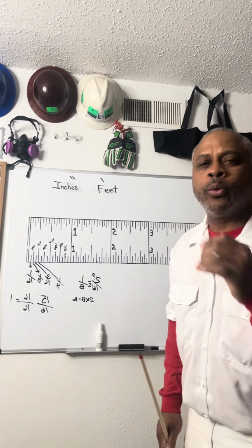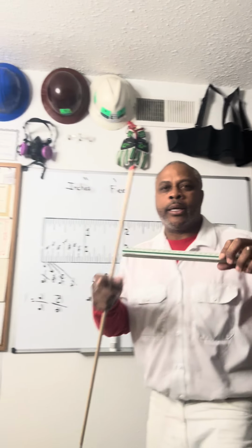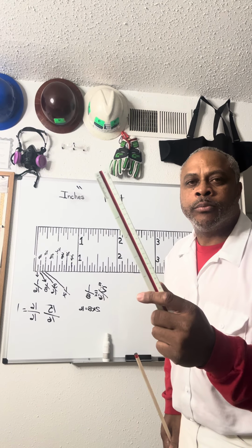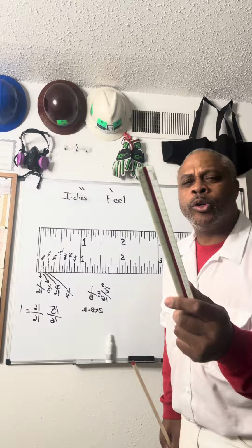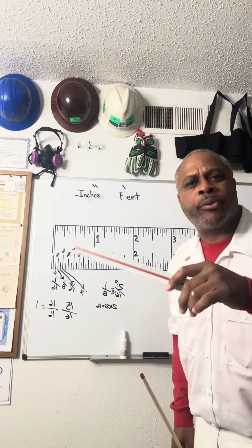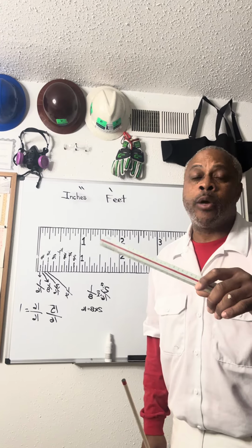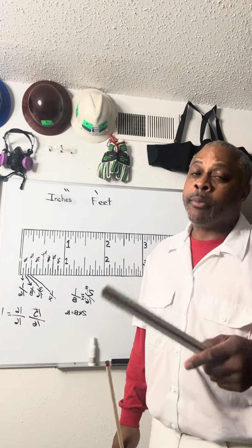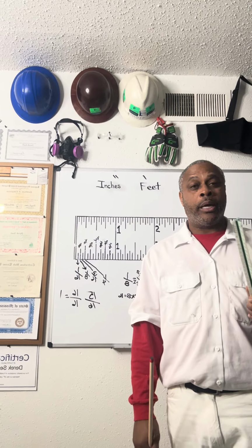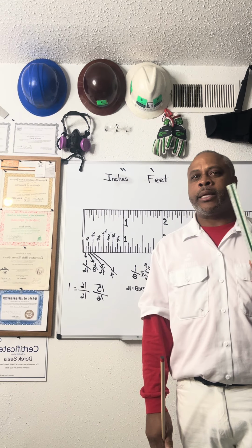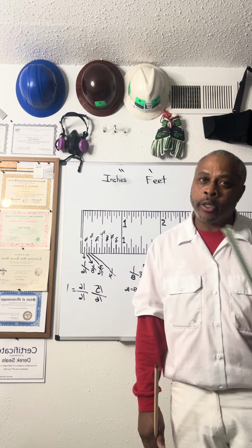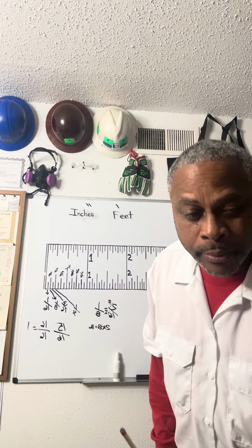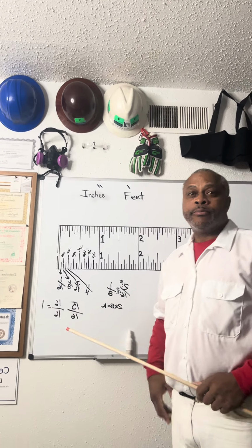We're going to take you through how to read a scale, okay? Because you can take this scale and you can put it on blueprints, actual blueprints, when there's not a number provided by the architect. And sometimes you're going to come across that, and I will be able to show you that a lot of things are not on the plans that you thought could be on the plan, which is going to leave you out there in outer space. And you're going to have to figure it out.